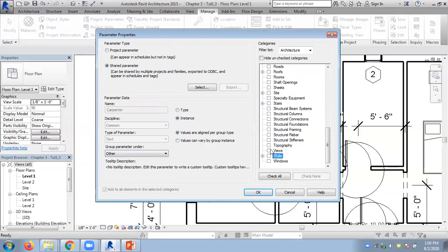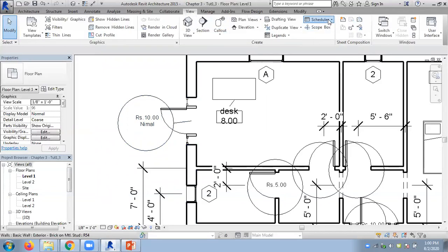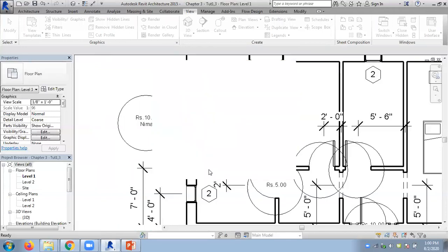Say we'll give it to a staircase. It's already there. So I added this parameter earlier also. So now they are not allowing me. So I will show you this one again next day, how to do it. For the time being, just understand parameters can be created, and these parameters can be taken to the QS table. So next day I will discuss these QS tables also, how to get the schedules.